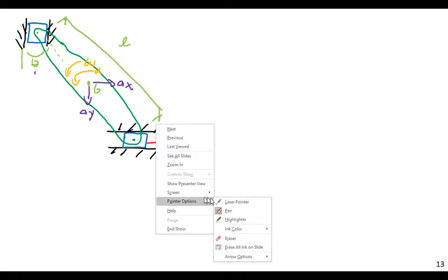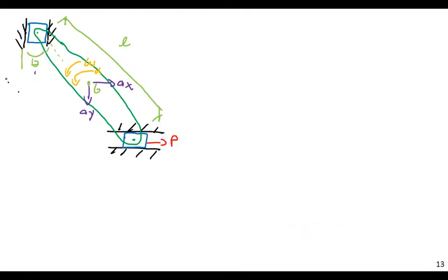The reason it's called constrained motion is that it is not free, it's stuck in these channels. In this case, A is going to be some function of theta, omega, and alpha. And here, this will be the same thing. It will be some function of theta, omega, and alpha. This is what it means to be constrained motion. In other words, if I know what angle this thing is at, I already know its position, don't I? Assuming this is a rigid rod that can't stretch or compress, if I know the angle, I can find this one and this one.